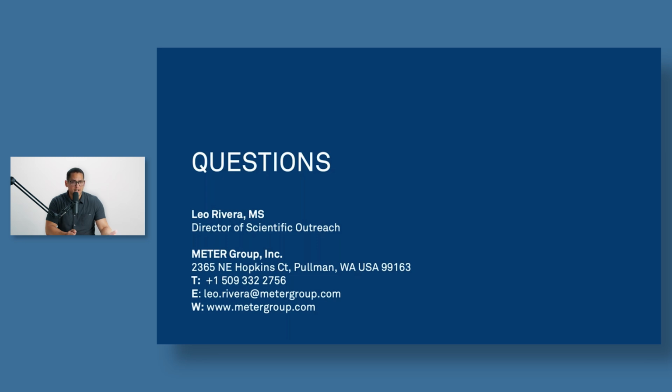So if you have that, then you can actually get your matric potential with the field sensor, whether it's a solid matrix or a tensiometer. I would really define that depending on what the range of water potentials that you're looking at. And then with the water content and EC measurement, then you can actually model out the saturated extract EC, and then actually model out what the osmotic potential is at that given point.